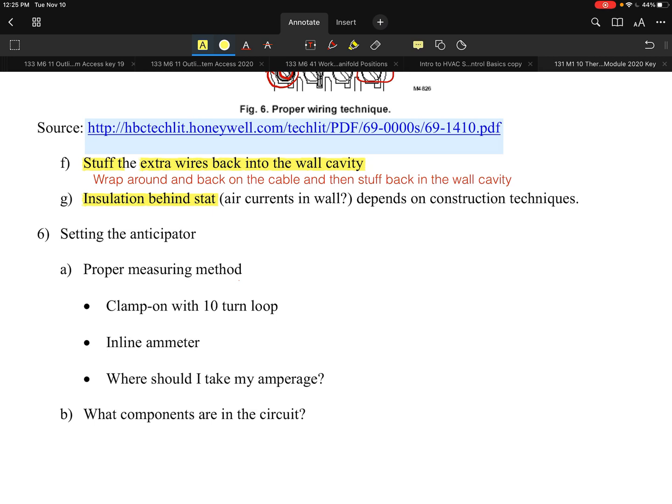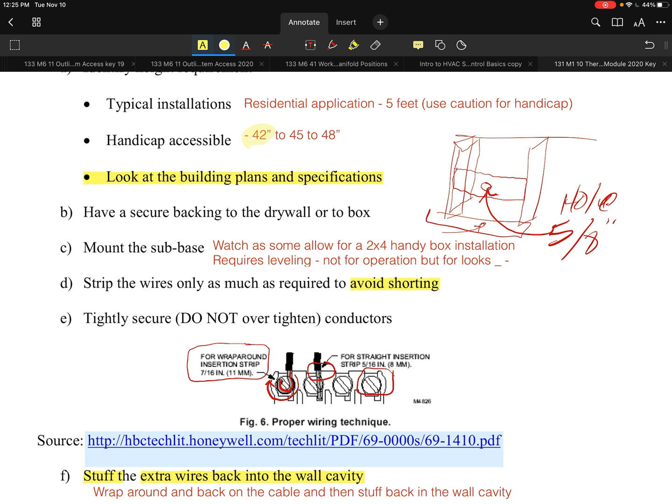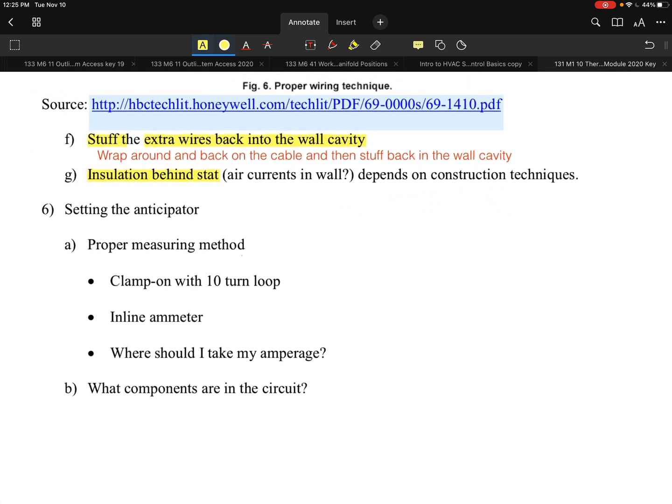Now, of course, the point that I want to make on the air currents in the wall is what every inspector should typically be doing: they would require that those holes be plugged up. All of this is about if there would ever be a fire between floor levels. What they don't want to have happen is one level of a floor, or a basement or a crawl space, feeding oxygen to a fire in a different level, and that's one of the reasons why they're doing that.